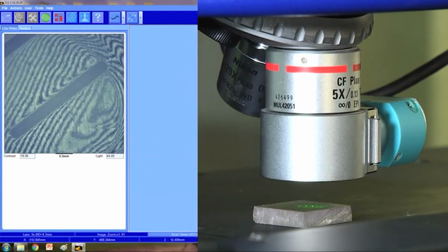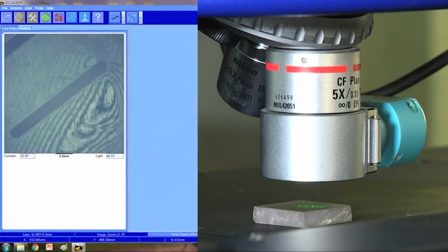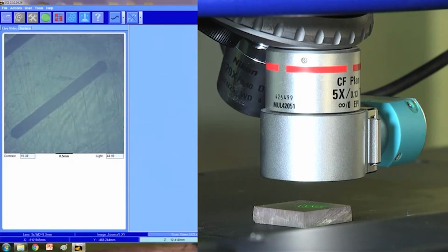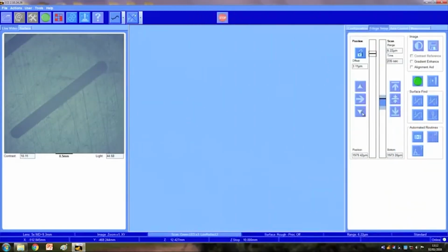These are the fringes created on the top surface. These fringes mean your surface is captured by the microscope reference surface. This is the top surface right now. We have to create a benchmark for the top surface measurement, and then we go gradually down to get the bottom surface. Since the bottom surface is very narrow, you will find a smaller amount of fringes, but that is enough to capture the required details.